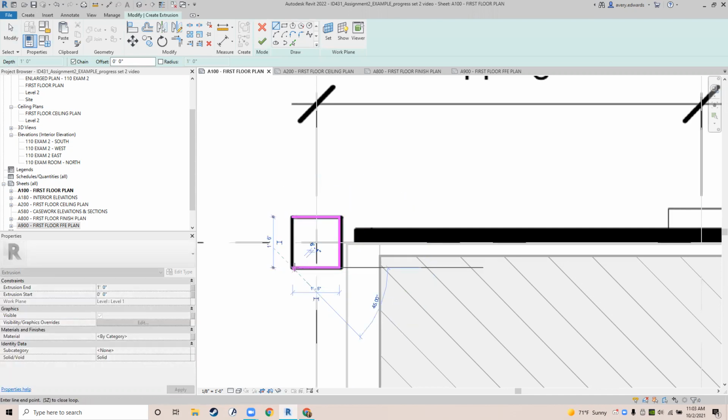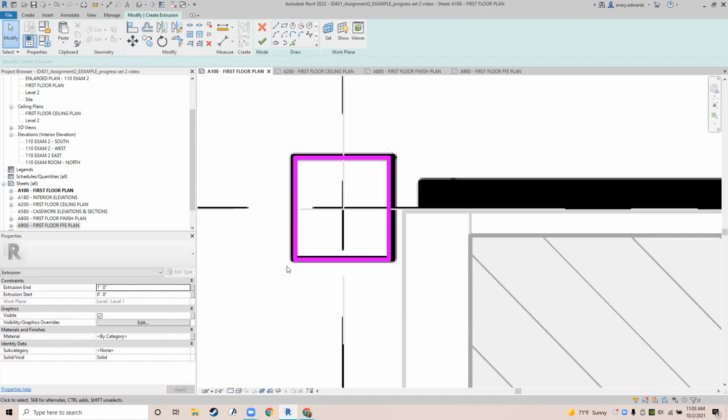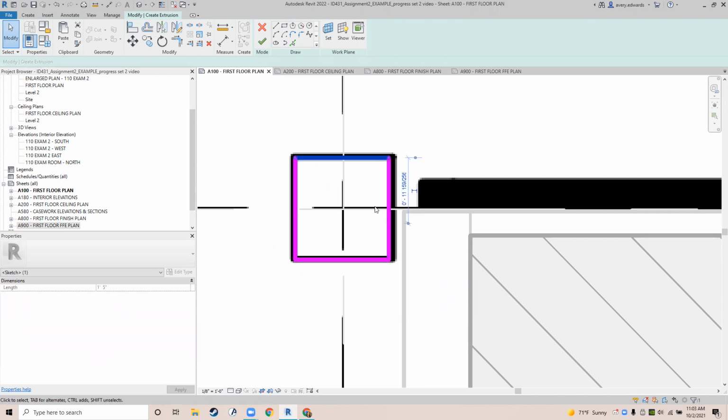Another best practices kind of thing is when you're drawing, even if you don't know the size of something yet, like when we drew off of the PDF, you should never have dimensions that look like this. You should never draw things that are just willy-nilly, like to the 256th of an inch, because obviously that's not realistic. Even though you don't know the measurement, you know that that's not what the dimension is really going to be in real life. Generally the smallest things ever get is 1/8 of an inch, because it's just not realistic for a contractor to construct anything more accurately than 1/8 of an inch.